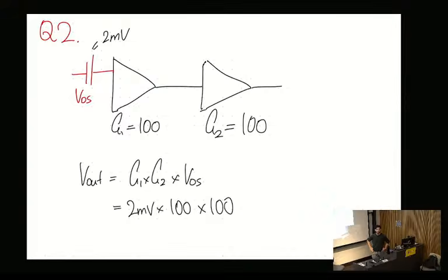So we're dealing with very small signals. And so if we don't get rid of the offset, that means the offset is almost comparable to our small signal. So it's really important to calibrate it away, even if it looks initially quite small. Okay.